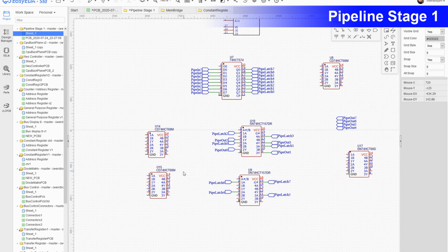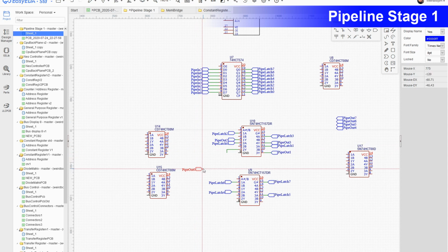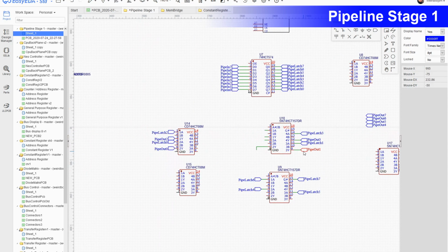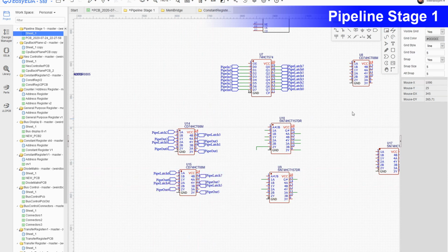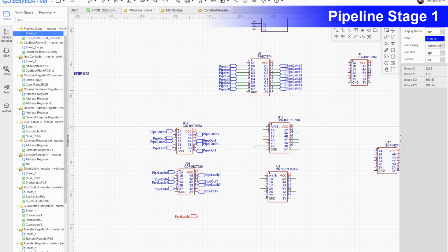Yeah, if I use an AND gate and wire all the B channels together, that'll work just as well, but it'll be a smaller footprint. Can't forget this is inverted from what I was planning, so let's call this pass out.